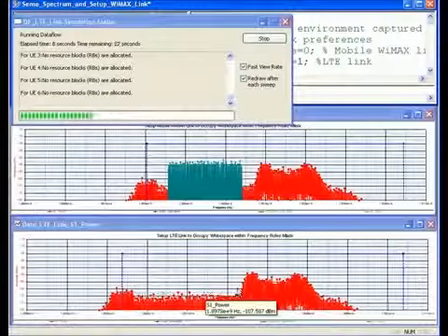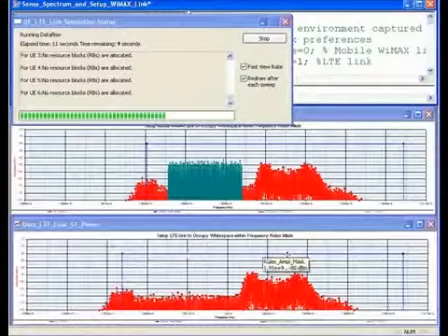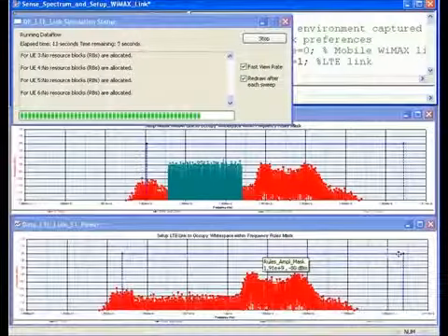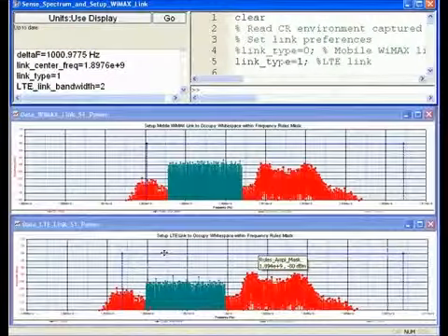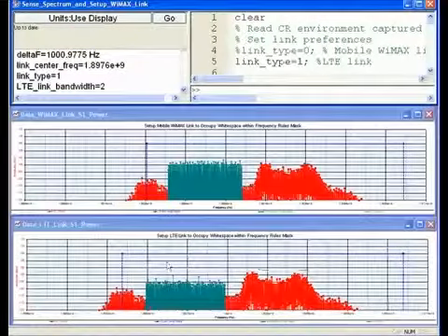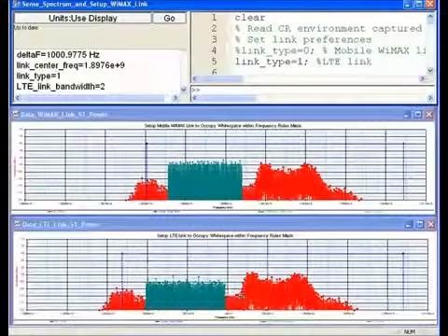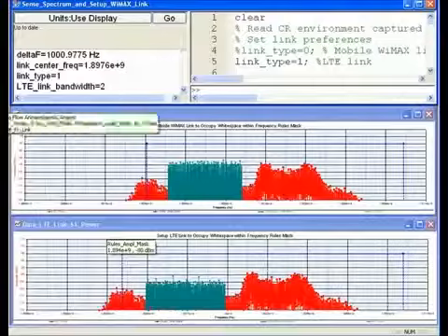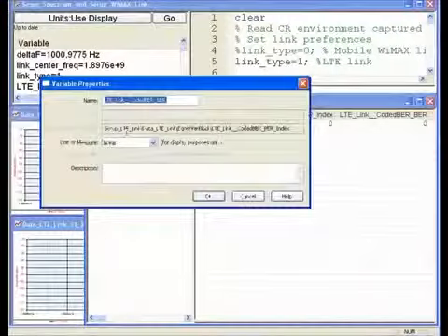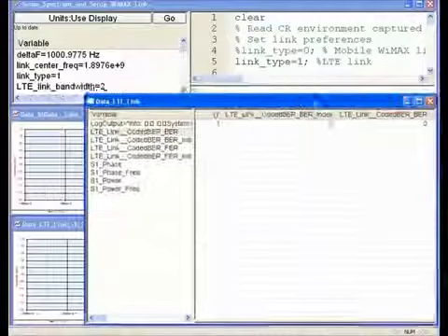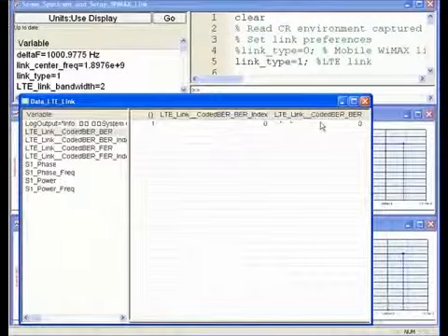The white space algorithm will determine the available white space between the two spectral peaks, but then it'll try to compute whether or not that white space is valid by comparing against a frequency policy, which is shown graphically by the dashed blue line. So here we can see the LTE simulation has completed, and as a result, it has centered an LTE spectrum between the two spectral peaks. If I open up the data set for the LTE analysis, and let's go ahead and bring up bit error rate, we can see that the coded bit error rate of the LTE link is 0%.